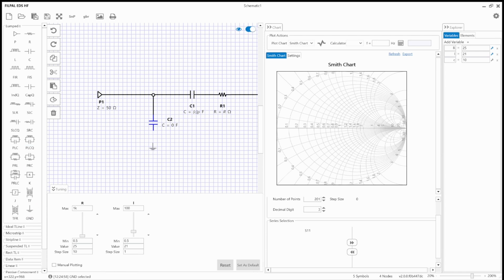and move down means it will move clockwise, and if it is inductor, it will move counterclockwise. So capacitor clockwise, inductor is counterclockwise. So now I make it a P, C in picofarad. And before I plot this, let me show you the one without this first, and where is the point. So now the point is here, and when I add a capacitor,